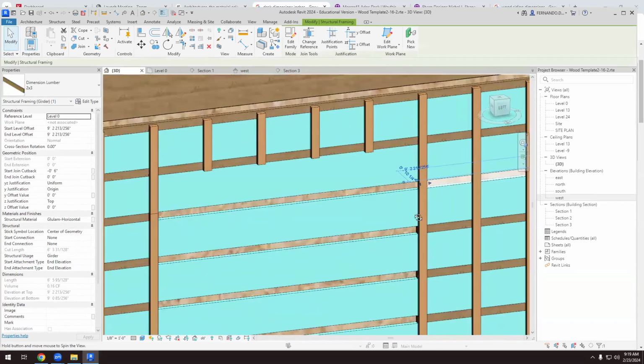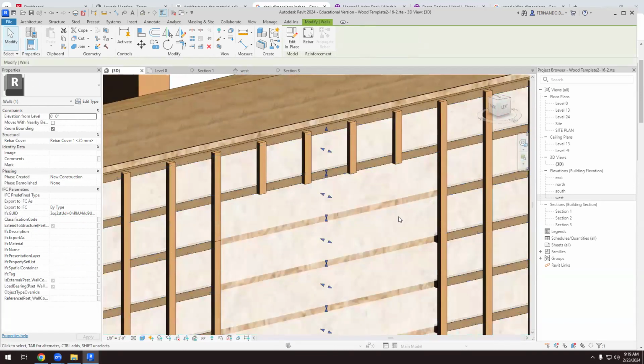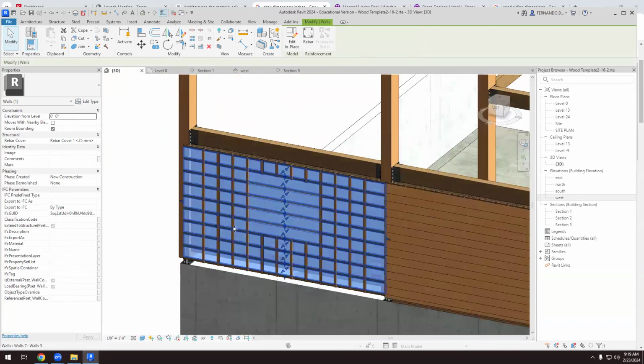That's the horizontal element. I split it. That's the vertical element. I split it. But now we have the thermal insulation. I can't split because it's a component model in place. Okay, so I have to create a void. I have something solid, and if I want to go through it, I have to create a void.